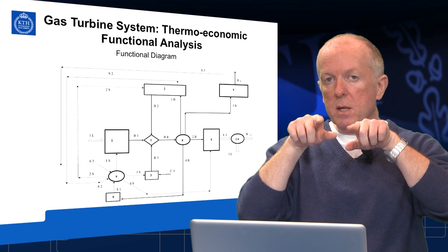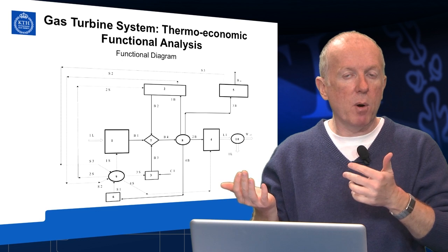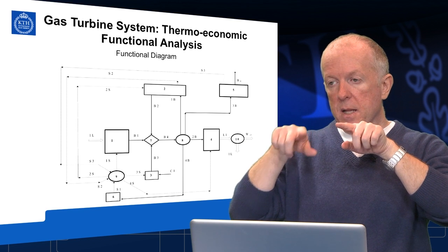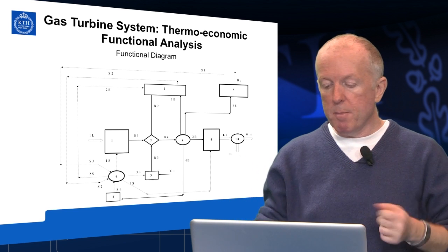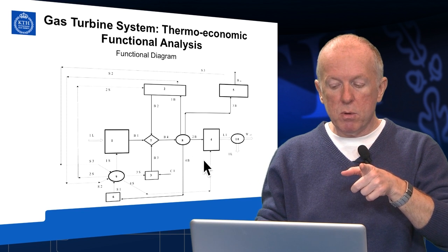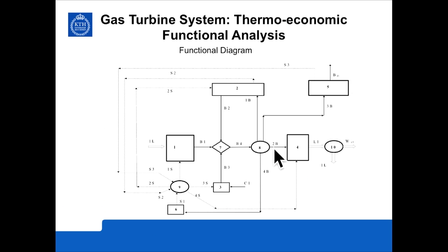This exergy is distributed to the components which are in cascade after this point, which are the gas turbine, the hot part of the air preheater, and finally the heat recovery steam generator. So B4 is branched into several components. B4 is split first into a resource 2B, which is given to the expander number 4. The expander produces the power L1 as a product. Please notice that the expander also receives a fuel in terms of negentropy, which is this line.